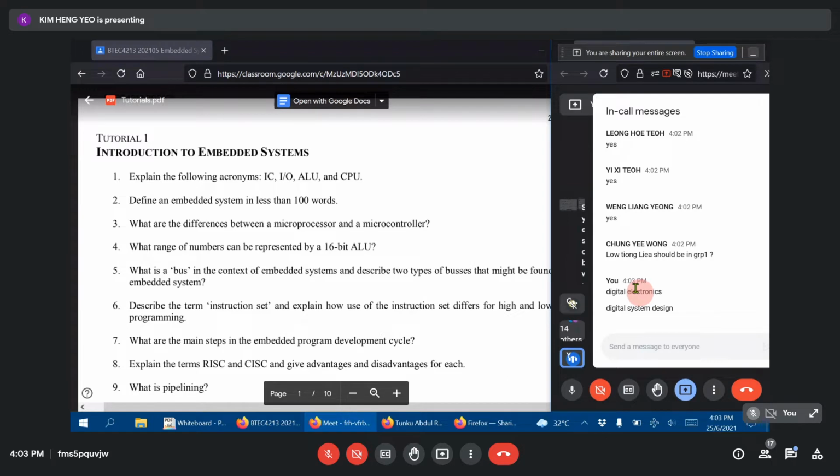Logic gates are built from transistors. At the lowest level, you have transistors. You add 4 to 6 transistors together, you wire them together, you get a logic gate. And you wire a few logic gates together, you get flip-flops. Flip-flops retain information. They are called memory elements. And you use logic gates and flip-flops to build two types of circuits: combinatorial logic circuit and sequential logic circuit.